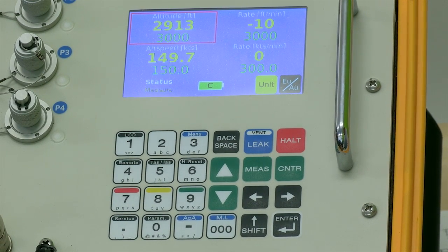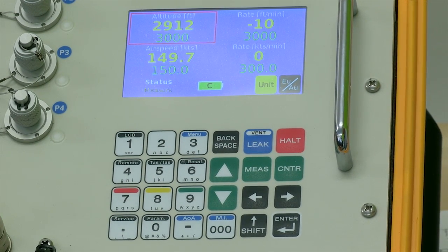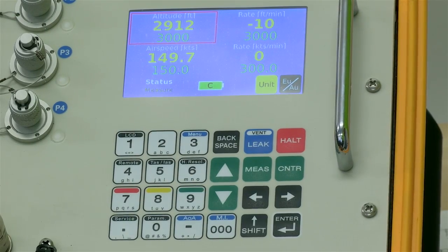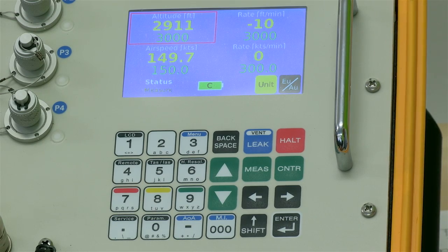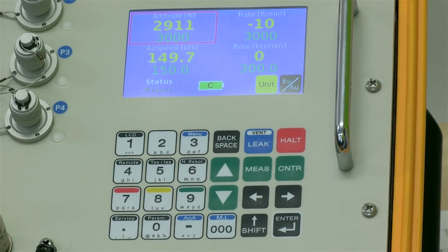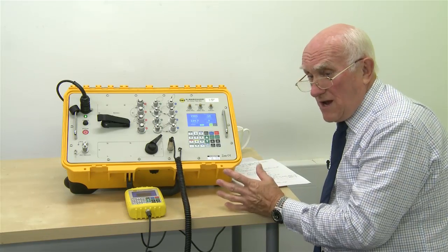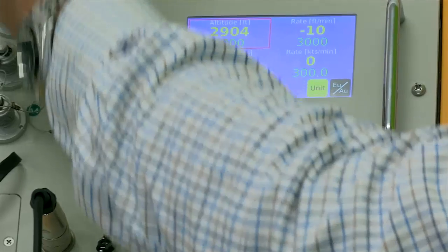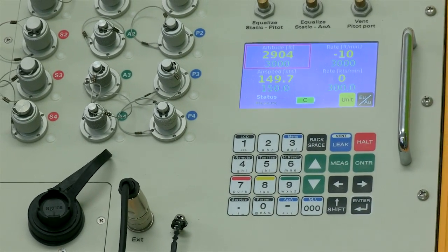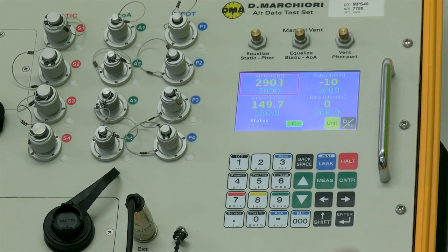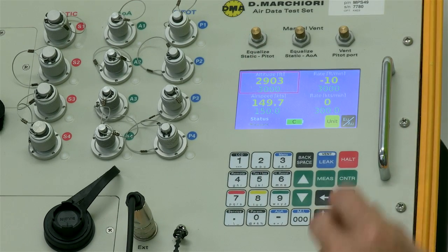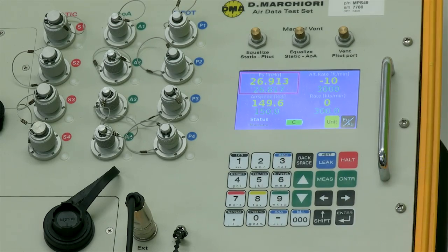The 49, the 3-channel instrument that has also angle of attack, you have a different situation in that you can now go in and address the angle of attack capability. So we'll do that now. Okay, just to show you how it works on the angle of attack, remember we've now got that other row, that 3rd channel. We could go, just for the moment, to altitude, and I'm going to go to engineering units, because with the angle of attack you're going to be putting in as demand values pressure values, not true angles in degrees.